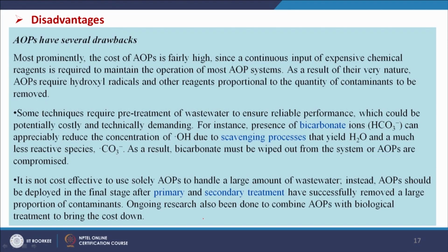AOPs have some disadvantages also. Most prominently, the cost of AOPs is fairly high, since a continuous input of expensive chemical reagent is required to maintain the operation of most AOP systems. By their very nature, AOPs require hydroxyl radicals and other reagents proportional to the quantity of contaminants to be removed. So, the selection of the dose etcetera is also an issue, and some techniques require pretreatment of wastewater to ensure reliable performance, which could be potentially costly and technically demanding.